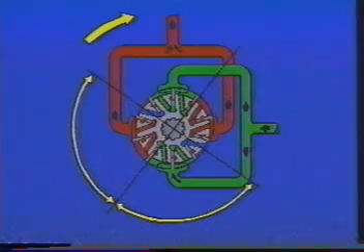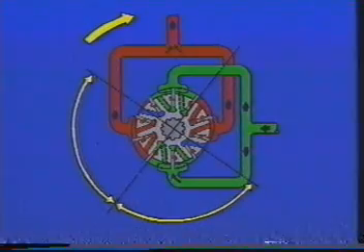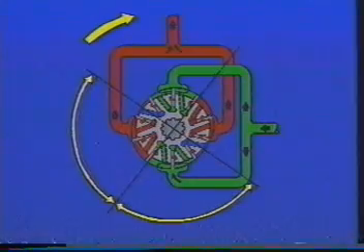As a remedy, holes were drilled through each rotor section, extending from its outer surface to the bottom of the vane slot ahead of it. By chamfering the tip of each vane, the pressure in the chamber behind it acted on both its top and bottom surfaces, keeping it in hydraulic balance.